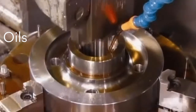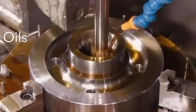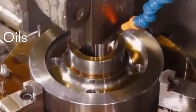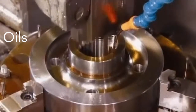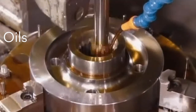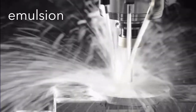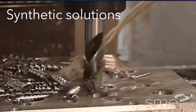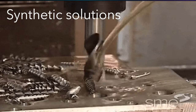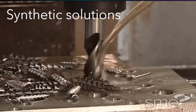Various types of metalworking fluids are now available with diverse chemistries, properties, and characteristics that fulfill these requirements. The oils maintain a high film strength on the surfaces of the metals, as can readily be observed when trying to clean an oily surface. An emulsion is a mixture of two immiscible liquids, usually oil and water, in various proportions, along with some additives. The synthetic solutions are chemical fluids that contain inorganics and other chemicals dissolved in water. They do not contain any mineral oils.